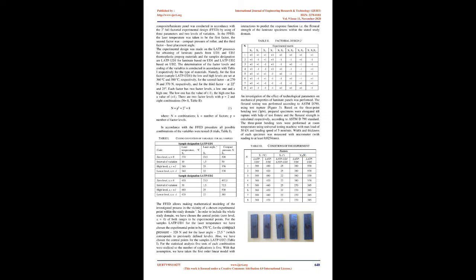2. Experiment. In this study, for the production of the thermoplastic composite panels, two types of thermoplastic unidirectional prepreg materials, UD1 and UD2, were used. UD1 and UD2 prepreg materials are based on AS4 carbon fibers and thermoplastic matrices polyphenylene sulfide, PPS, Ticona 0214 PPS, and polyether ketone, PEEK, Victrex 150 PEEK, respectively for UD1 and UD2, and both supplied by Suprem, Switzerland. Composite panel specimens with different technological parameters were produced with the help of a laser-assisted automated tape placement head, LATP, manufactured by Mikrosam, Macedonia.